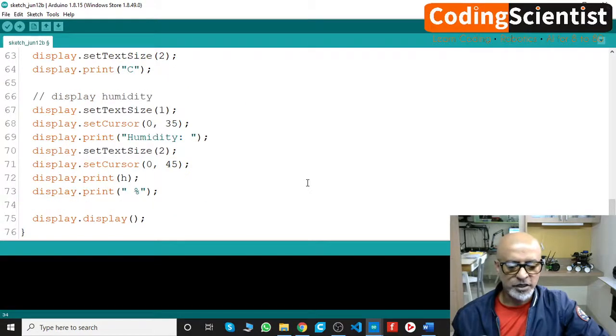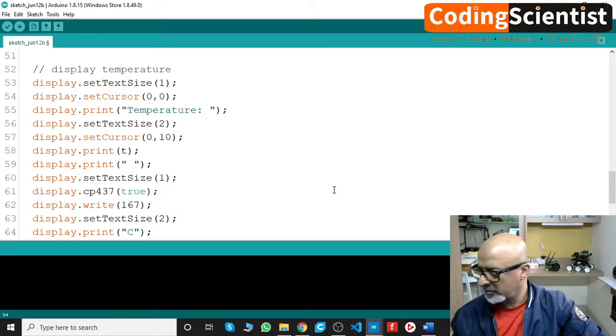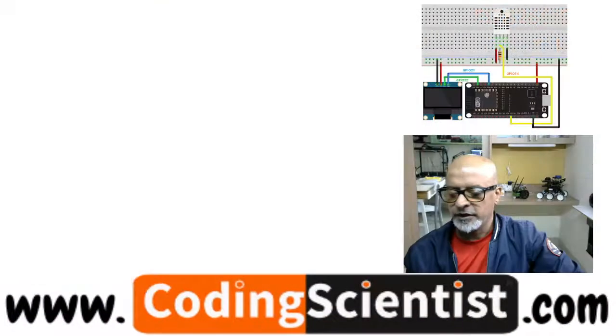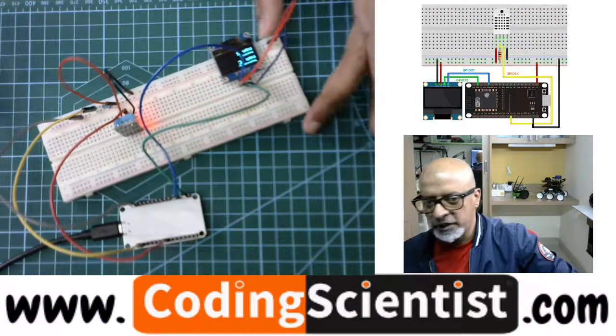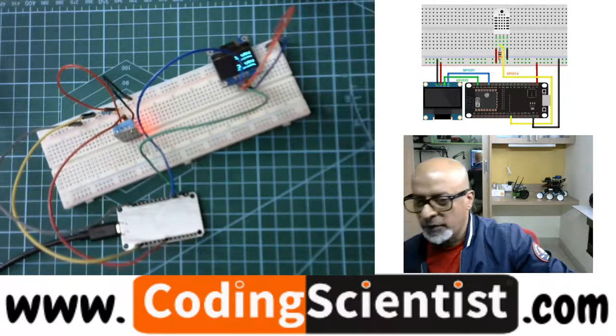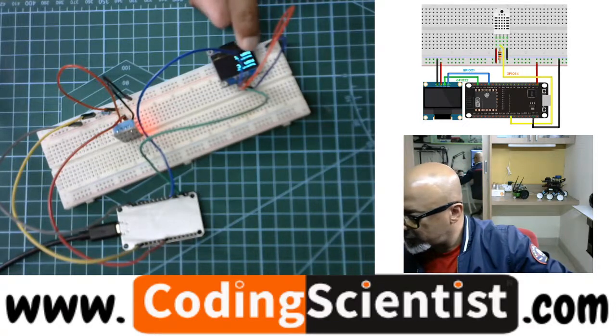Alright guys, so let's go ahead and upload. I have already uploaded this and I can see something blinking. Let me just show you my circuit. Okay, so I can see something is happening, but it's not reading the temperature. Why is it not reading? The good part is the OLED is working and I can see it's written as temperature none, and humidity none percent, temperature none percent.